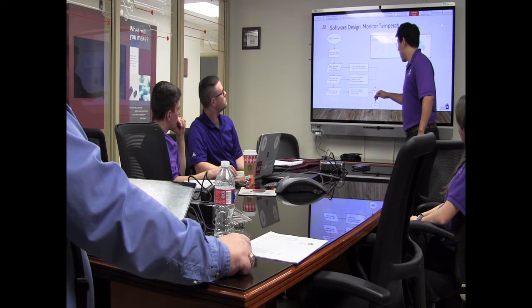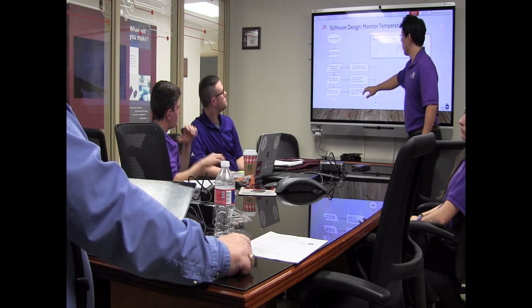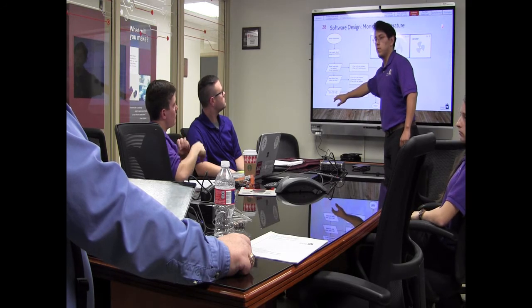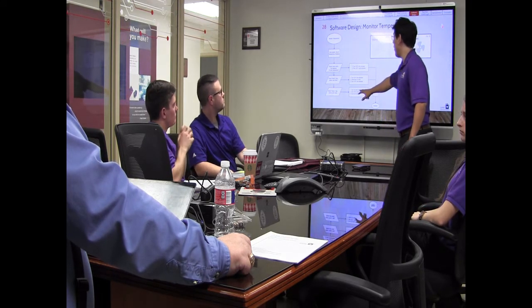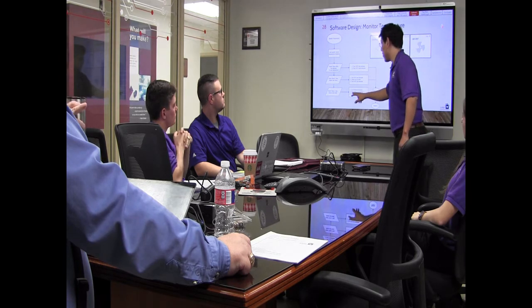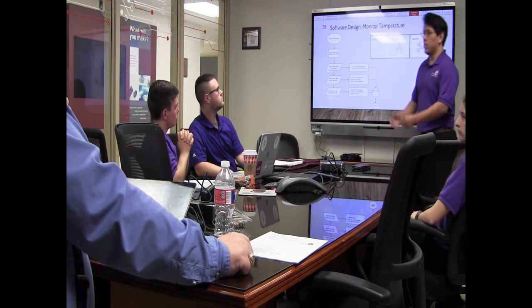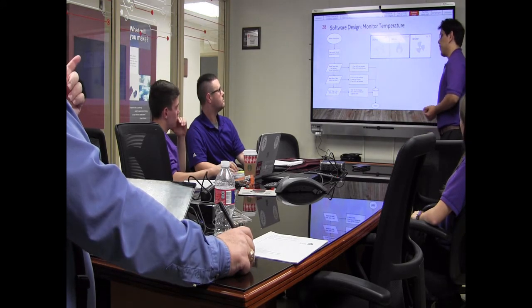And that gets stored. If the room temperature is 2 degrees above user temperature, that means it's too hot. So we turn on the hot indicator, correct? And then we turn off the cold indicator, and we open the air vent because it needs to. Okay, got it. Wait a minute though.